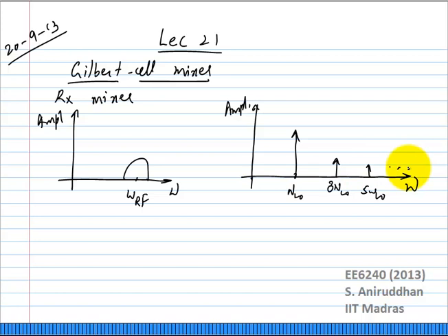square wave. Okay. So now you are going to give this to the RF signal. The first one, you are going to give this to the RF port, and you are going to give this to the LO port. Or you might give just a pure sinusoid, but the LO current looks like this. How do you look at the output signal, the IF signal in the frequency domain? In the time domain, you are multiplying these two signals. So in the frequency domain, you are going to convolve these two signals. So you are going to do a convolution of these two.